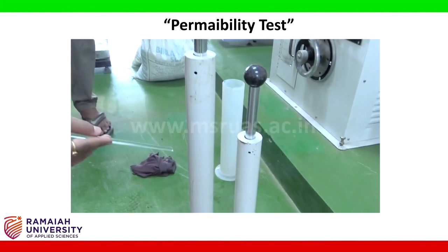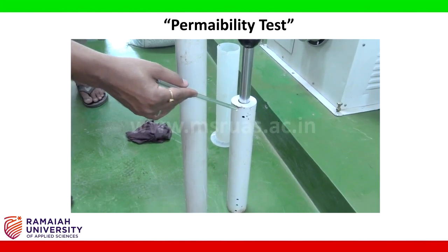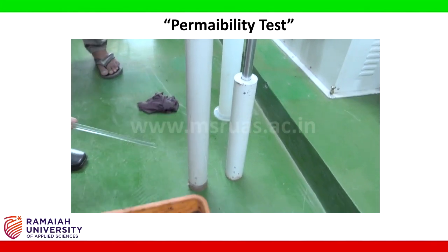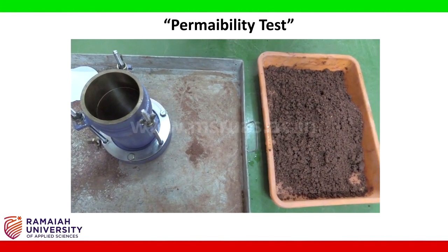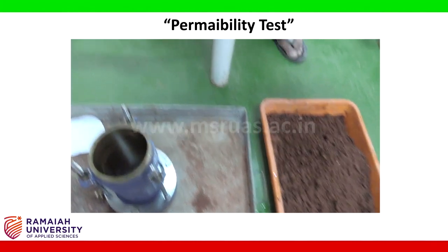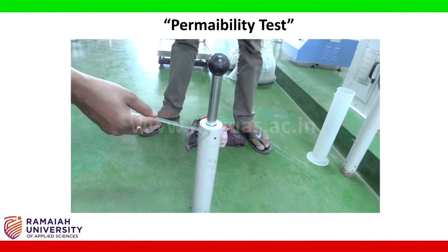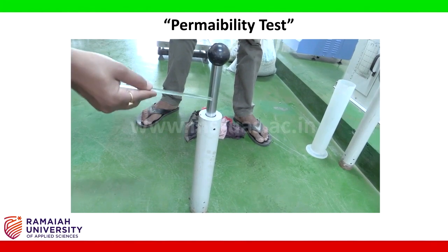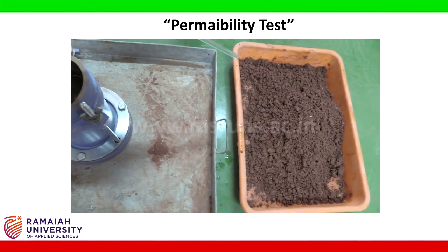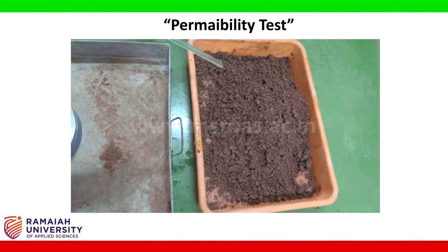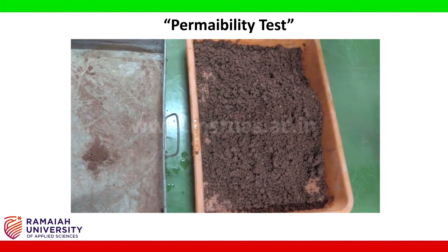Once we are clear with which rammer to use for the compaction process, we can now start with the compaction process. To begin with, I have assumed to use the light compaction process, and hence I am using a rammer weighing 2.6 kilos. The sample, which is now prepared by mixing with the water, shall be divided in 3 equal parts.